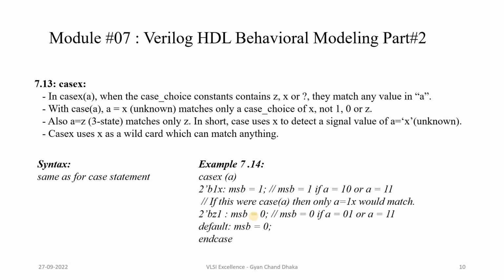Now let's see another type of case statement, which is casex. If we use the casex statement, the Z value, the X value and a character match symbol will be treated as a don't care. So if you use the casex statement, when the case choices are these ones.